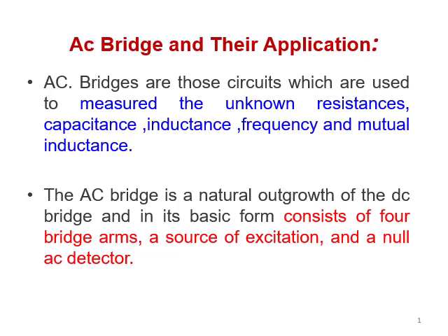Let us go now to the AC bridge. After understanding this DC bridge, we will go to the AC bridge. AC bridge is same as DC bridge. We are going to look for balance condition and so on, but if I need to measure the value of capacitor or inductor, you know, capacitor and inductor in DC circuit, they don't have effect. Capacitor will act as open circuit and inductor will be as short circuit. That's why they are not going to have effect.